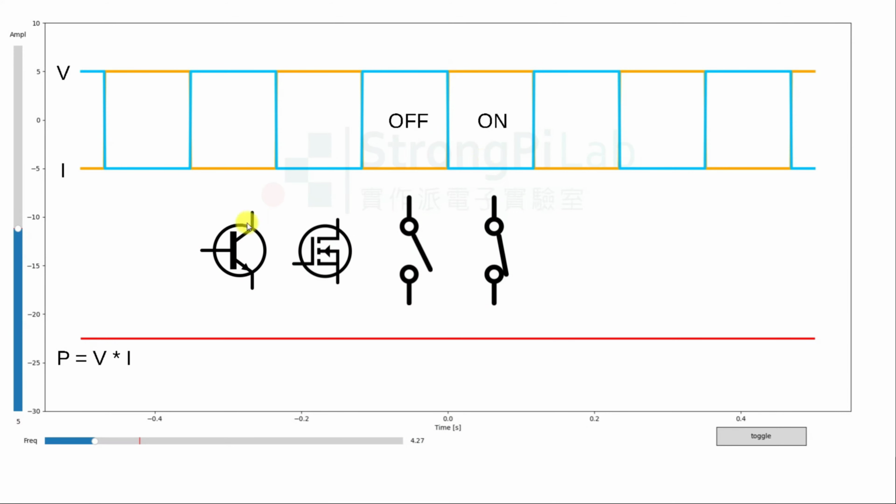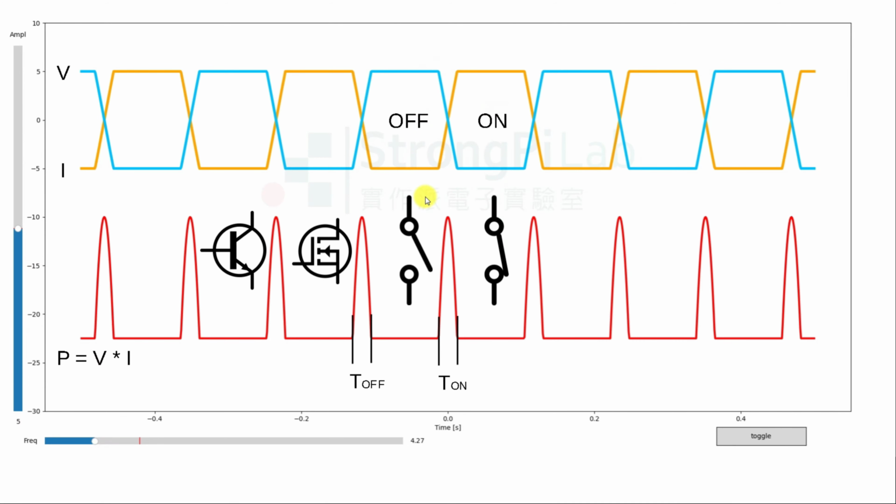When a general transistor is working in switching mode between on and off, the waveforms look like this. In the off period we have maximum voltage and minimum current. In the on period we have minimum voltage and maximum current. The transition edge waveform between on and off states isn't perfectly vertical, usually showing a noticeable slope. It looks like this. Here is a slope.